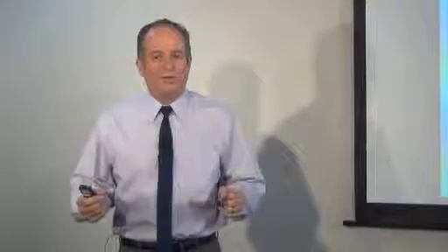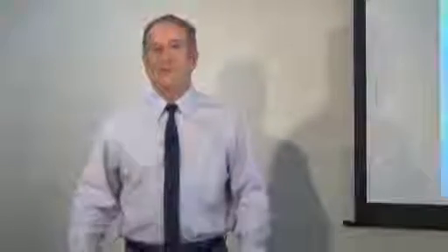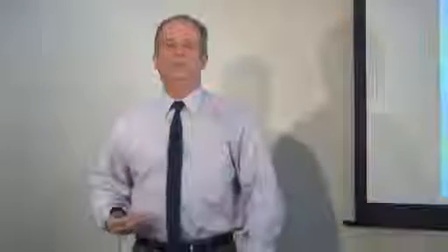The first one doesn't give you a lot of sense, but the second one does. It's 98% of the rated current. That tells you a lot. When you look at simulators, drawings, analysis, or power flow diagrams and you see what's going on, it's more important to know if you're close to capacity or not. And that's where the per unit system comes into play when you're a system operator.